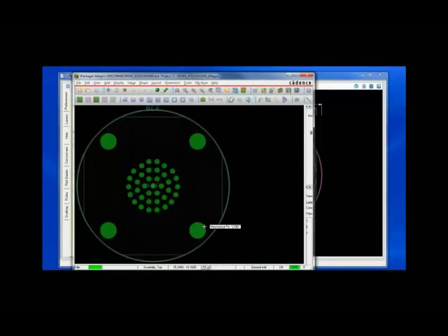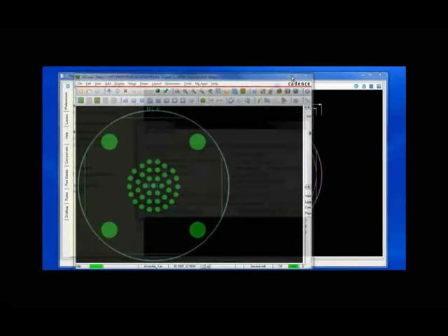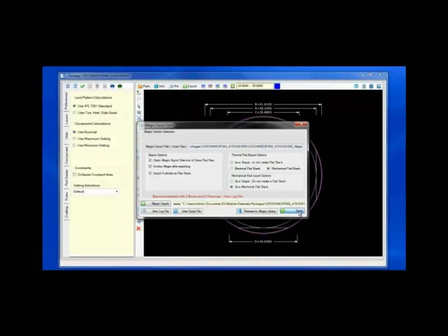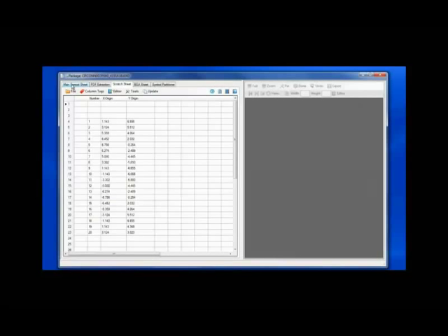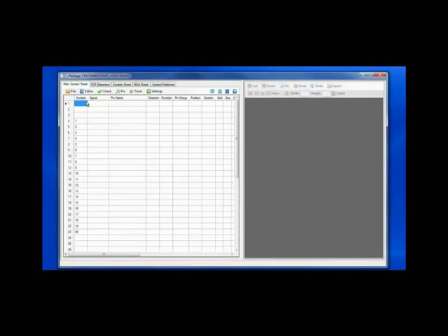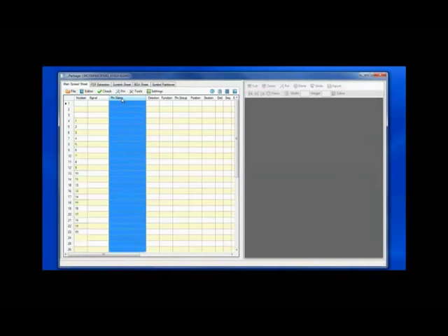Let's take down the Allegro tab, and the next step will be to model the symbol model. Selecting the configurator, I will move back to the symbol builder. In the Scratchpad spreadsheet, which we transferred to the main spreadsheet, we have the pin number, which I will copy the column into the pin name column.